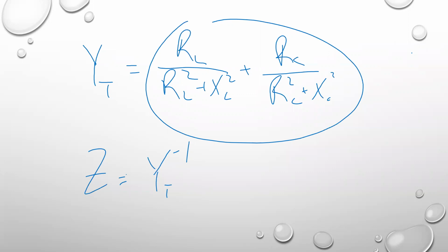The circuit is at resonance, and therefore the reactive portion is 0. We have said it several times. It means that the only power that is there is active power. So to ask whether we should be talking about the apparent or the active is somewhat redundant, because they must be one and the same. Because we are resonating, we only have active power. So it means that S would be equal to P plus j0.